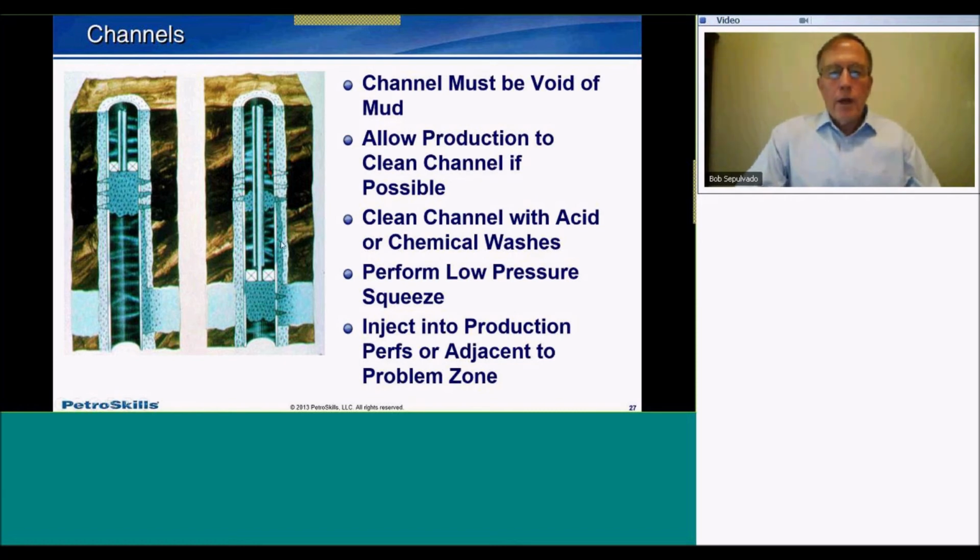The other thing with regard to this second method is that now we have additional holes in the casing that we have to deal with. So we have to be assured after this operation is complete that we have a competent seal through these perforations here as we begin to work production up here. So that's a circulation method on how to work through channels.